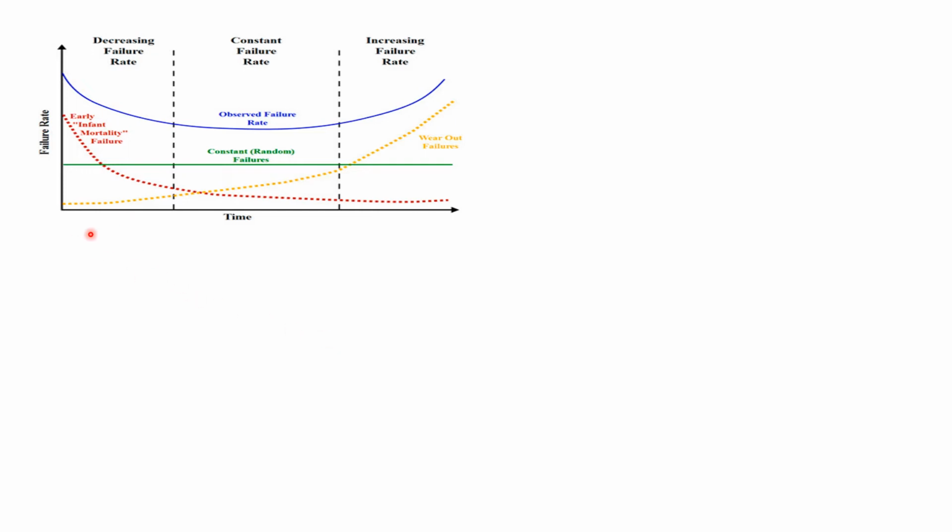So how this will affect is, like, the failure rate. Say this failure rate can happen through multiple failure mechanisms. That is what the HTOL testing will try to figure out. And one of these mechanisms is EM. So assume that we are figuring out the early mortality failures. This is very similar to infant mortality in children. Children usually have a high death rate in less than 11 days.